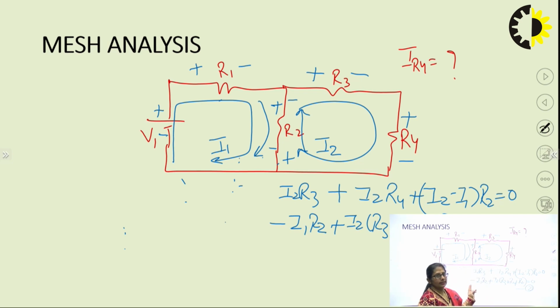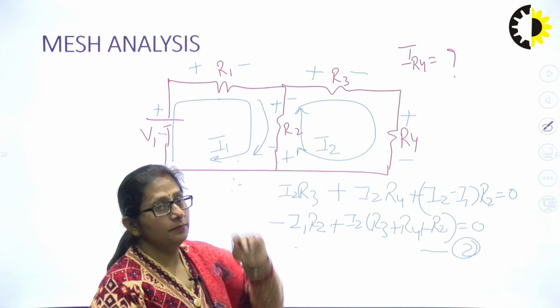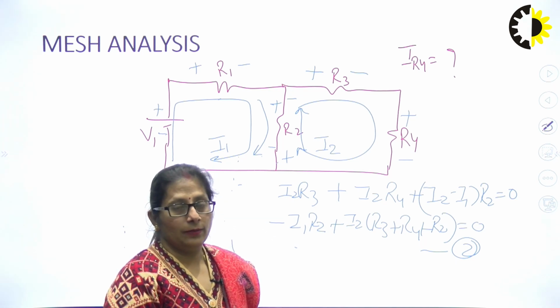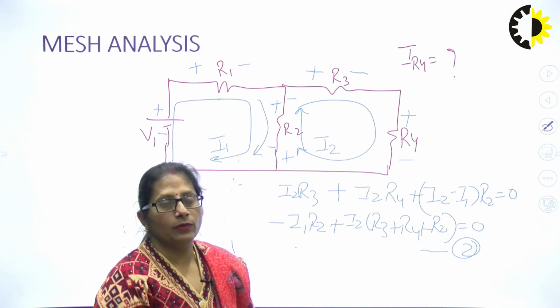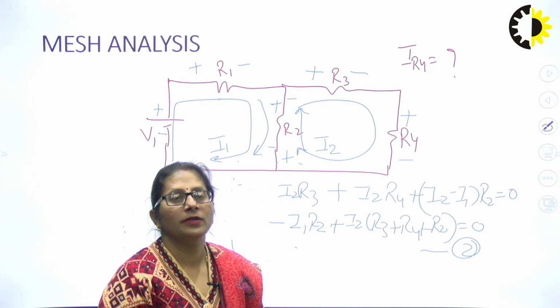So, I have resolved the earlier equation and the present equation in I1 and I2 form. I may be applying Cramer's rule, or I may be solving the 2 or 3 simultaneous equations without applying Cramer's rule also, and identify the value for I1 and I2. Now, once I get the value for I1 and I2, I may be finding the voltage across each element, the current through each element and the power drop across each element, right. So, every quantity can be found out once I am done with the currents in the 2 meshes. That is how we used to go for mesh analysis.